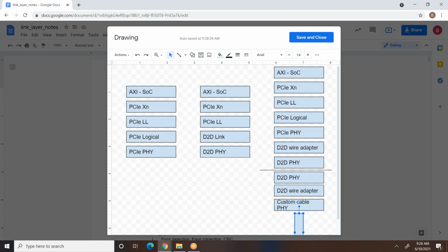So is this all on one chip? This is the chip boundary now. You certainly wouldn't have the PCIe PHY in there. Why would you have two PHYs? Because you're just taking your PCI controller, and you don't want to change anything. You're just taking your PCI controller as is. It's throwing out a bunch of wires, right? It's driving 16 lanes worth of something.